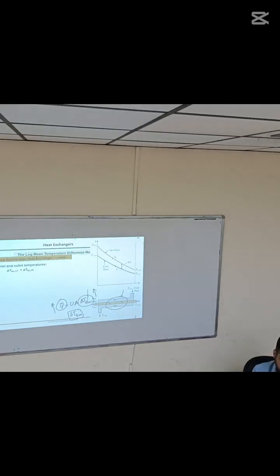But there are other issues. That's why we do not use counterflow, because here there are no fins, it's not cross flow. You need a very large length. That's why we go for the other types of heat exchangers, which we discussed yesterday. But as far as the delta TLM term is concerned, it will be highest for the double pipe counterflow heat exchanger.